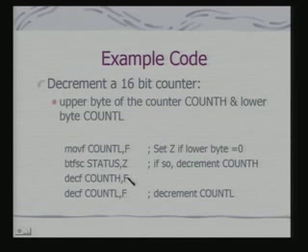We are checking that depending on the condition, we shall either decrement count L or decrement count H. Fine. Now the interesting feature is, if an interrupt occurs while this code is in execution, try to understand this, what can happen? Your decrement may not take place correctly, because your counter is not getting decremented by an atomic operation.